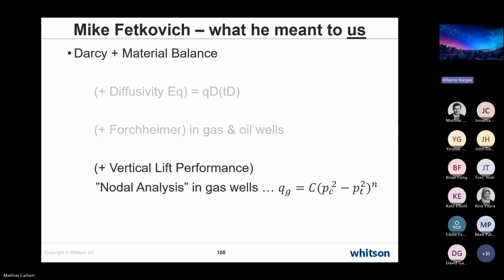behavior in oil wells. And then he also included a little bit of vertical performance and, in my opinion, produced the first kind of paper that talked about nodal analysis, where you couple the reservoir to the tubing and to the surface. And he had presented a paper on that as well. So these are some of the things that he presented to us.